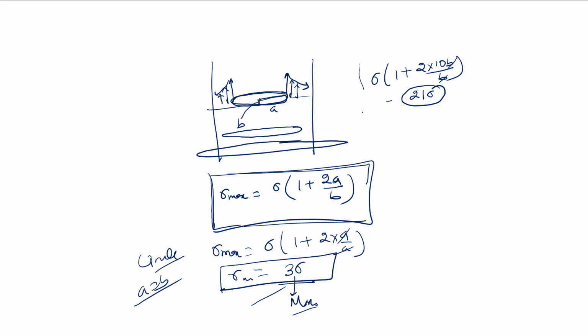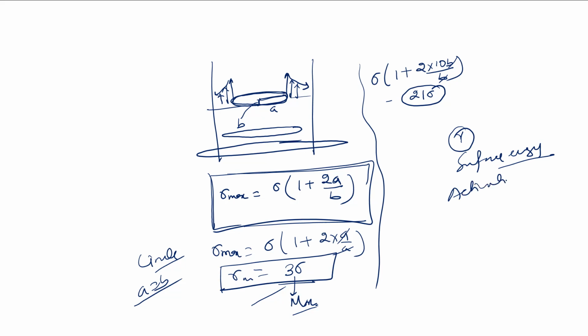This will be explained again in fracture mechanics: even though there are cracks, the crack size is a limitation. It has to have a certain size for the crack to propagate, because it is related to the surface energy of formation of the crack, and there is some activation energy which is needed.